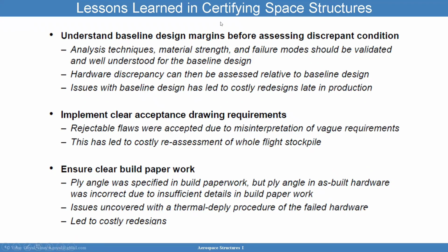Lesson learned in certifying space structure. You want to understand the baseline design margins before you assess a non-conformance. If you don't have a good understanding of baseline design margins, then assessing the non-conforming condition also becomes less clear. So analysis techniques, material strength, and failure mode should be carefully validated and well understood for the baseline design. Hardware discrepancy can then be assessed relative to the baseline design.